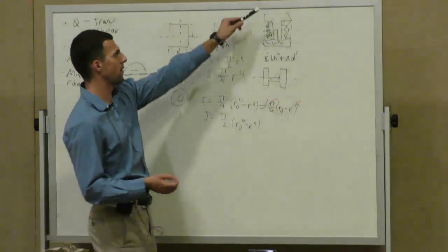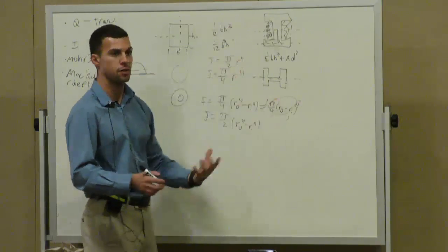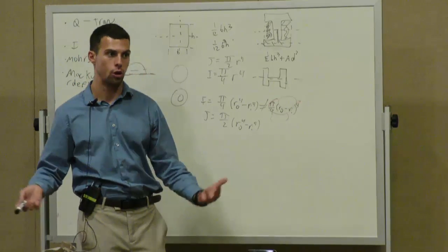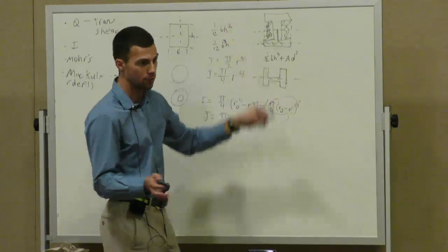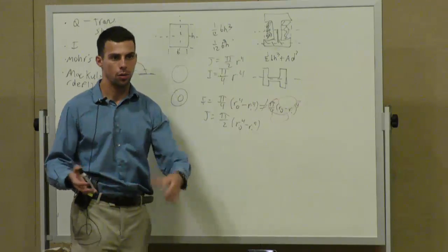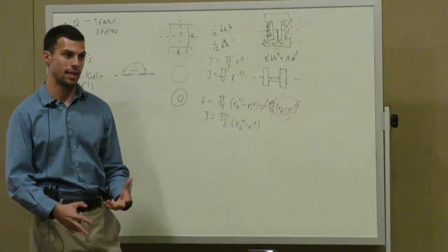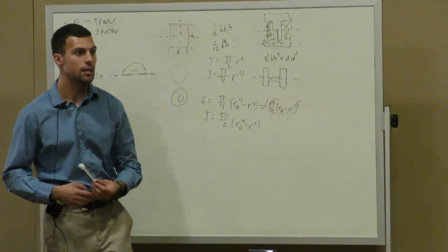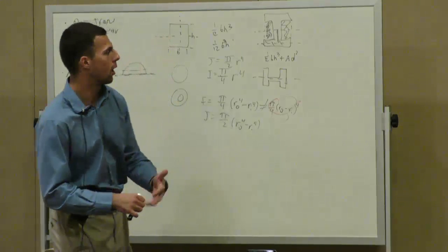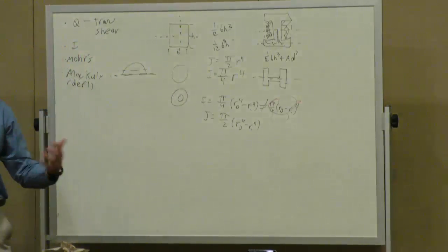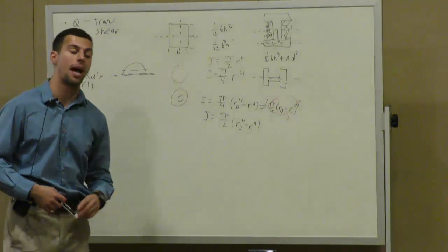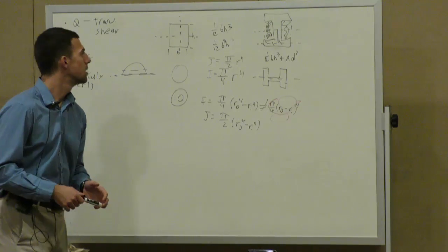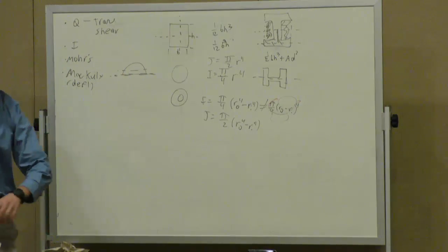In other words, if you have a composite shape, something made up of smaller parts, then the overall moment of inertia is equal to the sum of the moments of inertia of all those parts that make up the composite. Yes, that's what we were doing in dynamics. We also established a lot of that because it works the same for mass moment of inertias too. Are we comfortable with those I's now?